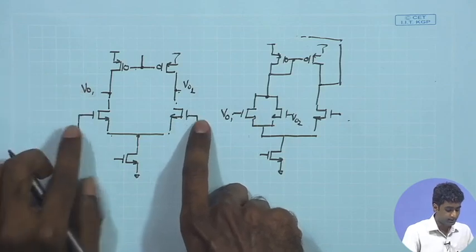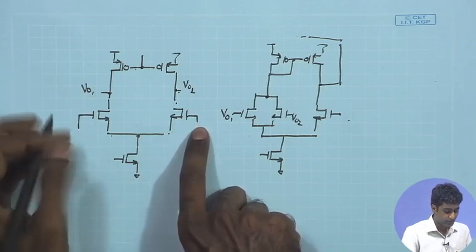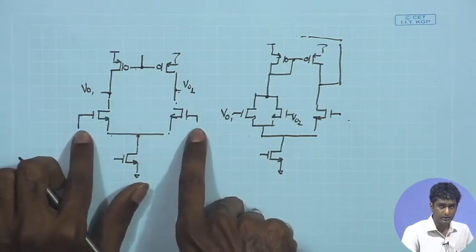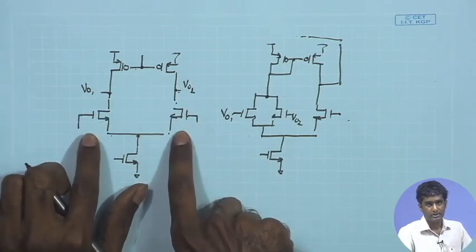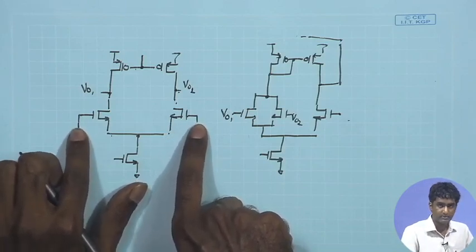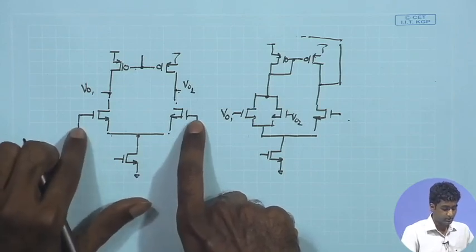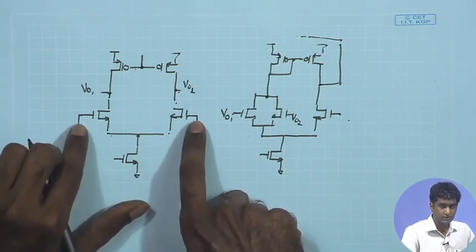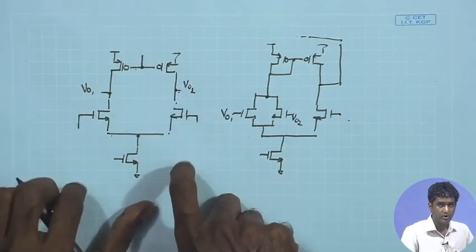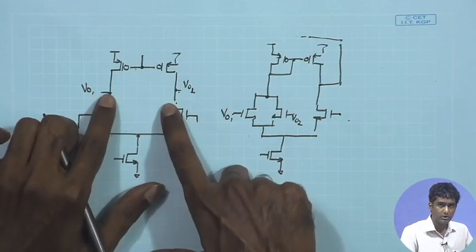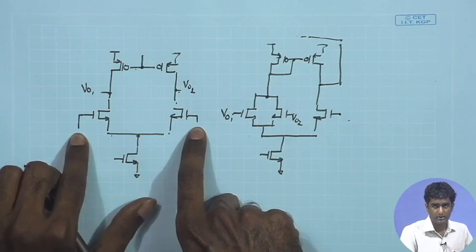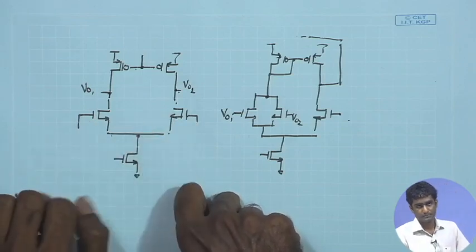However, if you look at the input signal over here, if you have an overall signal coming in, it will induce some signal at this point also, unless you have some significant input capacitance placed over here for establishing an AC ground. Therefore, in order to ensure that this point is at AC ground, either we need to put a capacitor over here along with the RF, or the other option is that you remove the RF and then apply only ideal DC voltages over here with values equal to the closed loop condition.